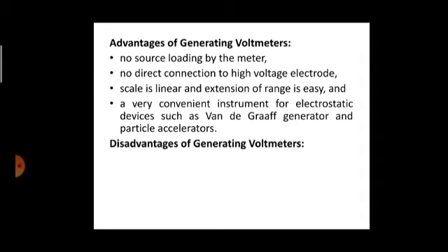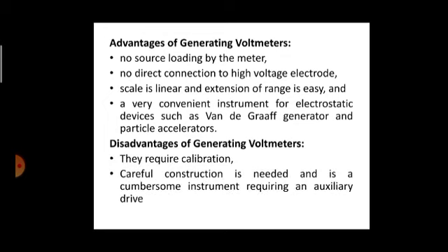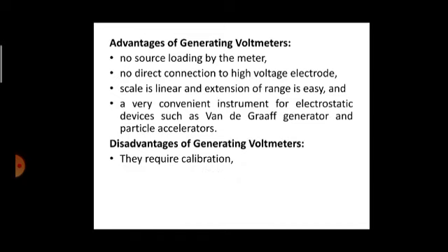Now talking about the disadvantages of generating voltmeters. First thing is, they require calibration. Every time you have to calibrate it. Careful construction is required, and it is a cumbersome instrument requiring an auxiliary drive, which is the motor we are using.